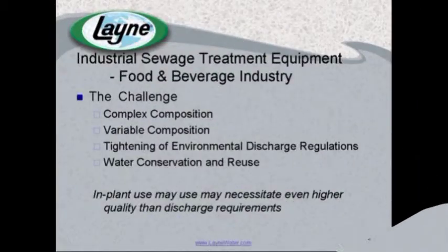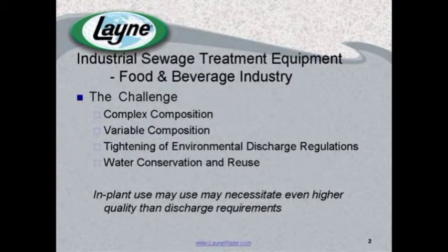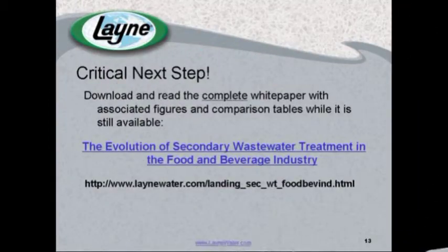So once you've moved through those 5 steps, you've really covered the overall waste treatment process. Again, starting at the beginning of the challenge, it's really that difference in composition, the fact that it's extremely variable and that the inlet streams to the process really have quite a high BOD and COD, as well as what's referred to as FOG, or fats, oils, and greases, when we're talking about a food wastewater stream.